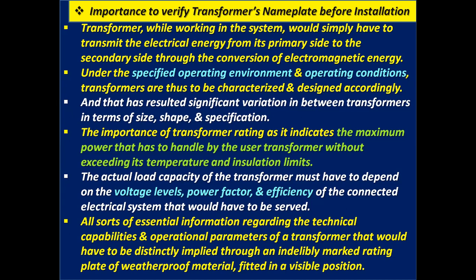The actual load capacity of the transformer must depend on the voltage levels, power factor, and efficiency of the connected electrical system that has to be served. All sorts of essential information regarding the technical capabilities and operational parameters of a transformer have to be distinctly implied through an indelibly marked rating plate of weatherproof material fitted in a visible position.